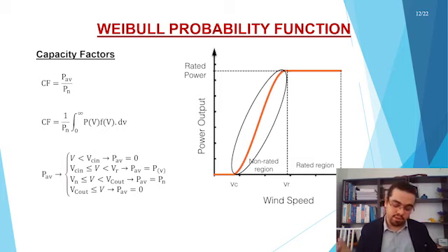and if it's higher than the nominal speed but lower than the cut-off speed, we get the fixed rated power output. If it's faster than the cut-off speed, it is 0 again. For this reason, we need to calculate the non-rated region as a function and put it into the process in this way.